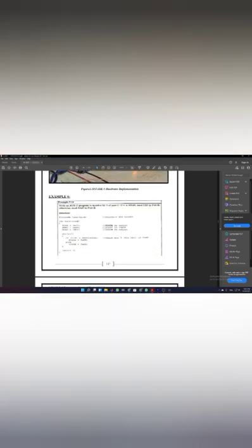Moving on to example number 6, in this example we have to write an AVR program to monitor the 5th bit of port C, as I explained previously. If it is high, then print 55 in hexadecimal to port B, otherwise send AA to port B. So we are declaring port B as an output, port C as an input, and port D again as an output.